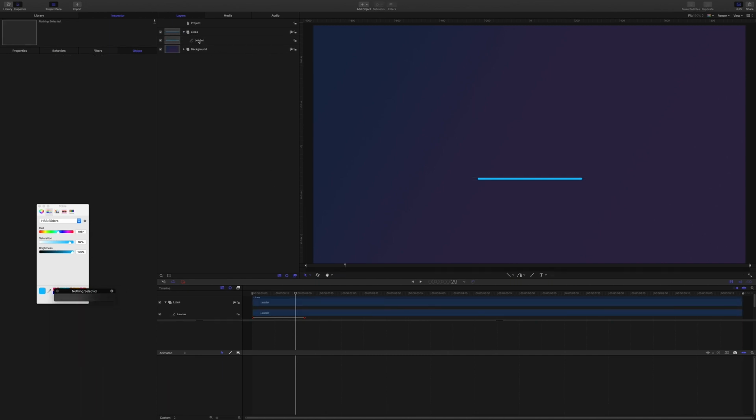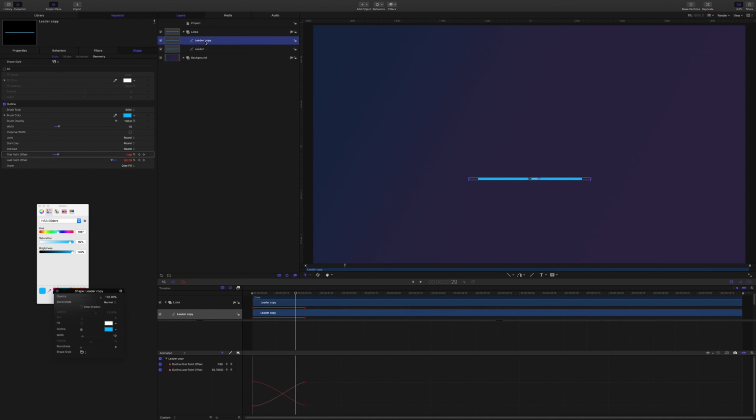Okay, so now I want to duplicate this, and I'm going to rename it as mask, because we're going to mask out that first line. So with the playhead at 5 frames, make sure that second line is selected, and on the keyboard hit the shift and left bracket key to move the endpoint of that element to the 5th frame.